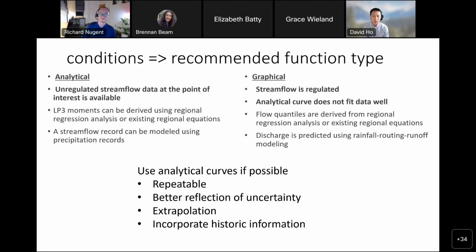So what a hydrologist can do is pretend that that reservoir did not exist by doing computer simulations to see what the flows might have looked like had that reservoir not been put in place. That's what we mean by unregulating the flows. And that's how hydrologists typically make the big bucks.